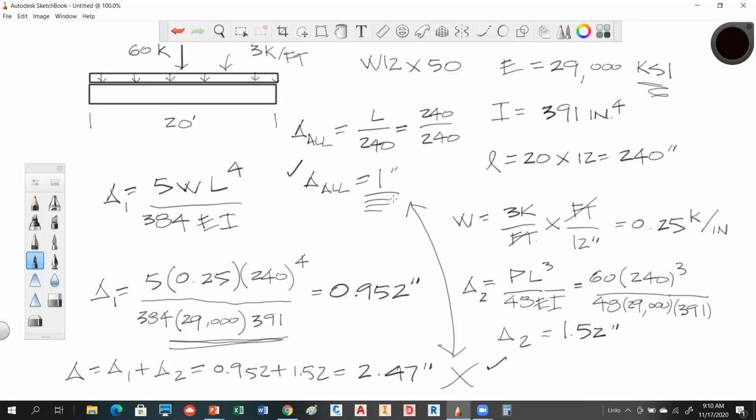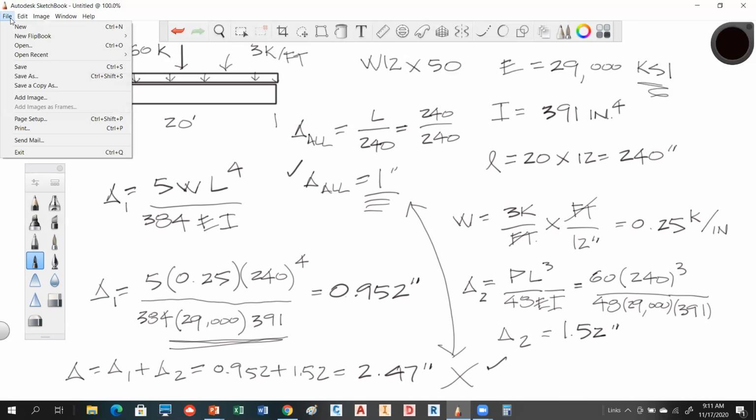In appendix D, what you'll notice, this is for timber design. And why that's important is in some of those designs that you're looking at in chapter 12, you're using wood or timber. Go to page 644, table D1, and you'll notice it gives you nominal size and then what's called dressed size. So when you're calculating cross-sectional areas, for instance, let's just clean this page up real quick.